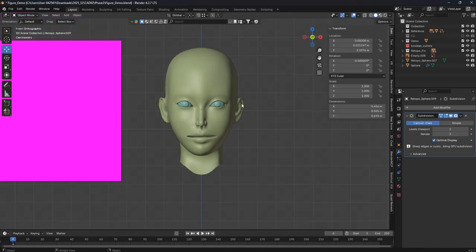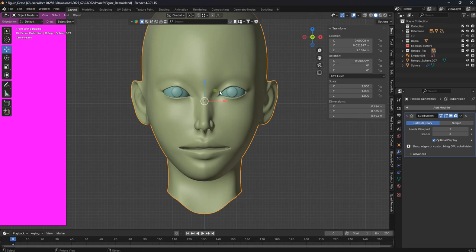So once you finish the topology and also the detail refining of your low poly model, then you can just directly apply the mirror modifier. So you can get the final one. Probably you may wonder, where is the eyebrow and eyelash? I mean, the eyebrow here and eyelash. So where is that? For that kind of thing, usually we will use a texture to do that.